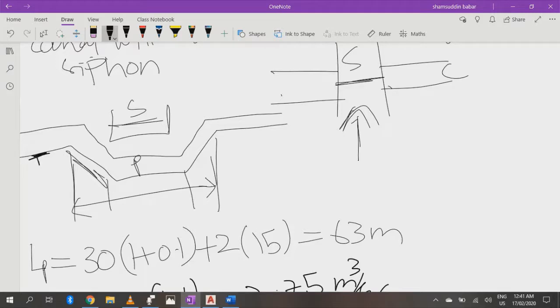Now this cross drainage structure is shifted from this point to about this point. So how much depth will this be? This is due to the scouring depth. Scouring means the water crossing this stream will actually touch the siphon if the siphon was here. So this will scour it.